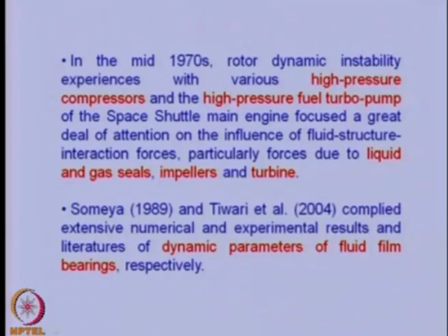In the mid 1970s, the rotor dynamic instability experiences with various high pressure compressors and high pressure fuel turbopumps of the space shuttle main engine focused a great deal of attention on the influence of fluid structure interaction forces, particularly forces due to liquid and gas seals, impellers and turbines. Someya in 1989 and Tiwari in 2004 compiled extensive numerical and experimental results and literature of dynamic parameters of fluid film bearings, respectively.